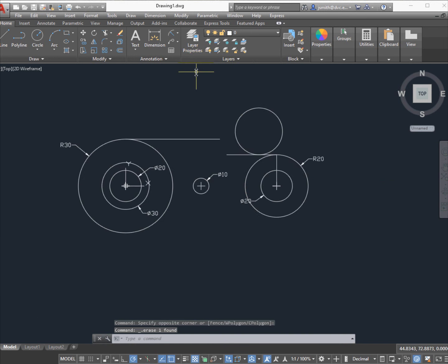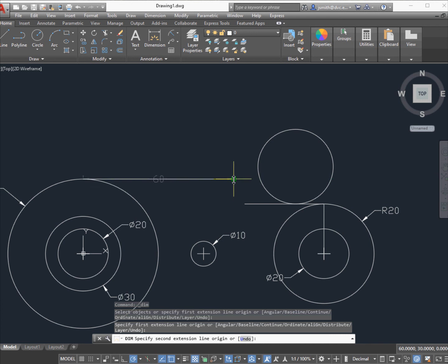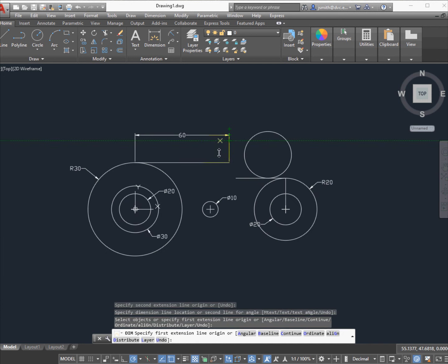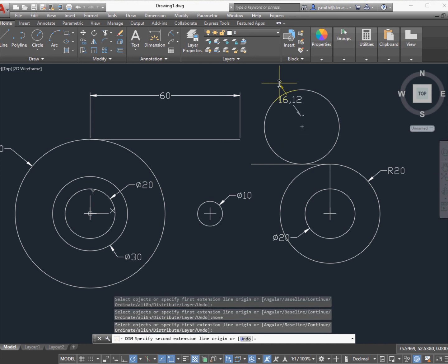Now, what I'm going to do is I need to move that over so it touches the line. And so let's go ahead and confirm the dimension of this, 60. That's accurate. And so I will type in the magic words move. All right, type in move, push enter, select a circle. And so it takes a couple tries of this. What I'm going to do,